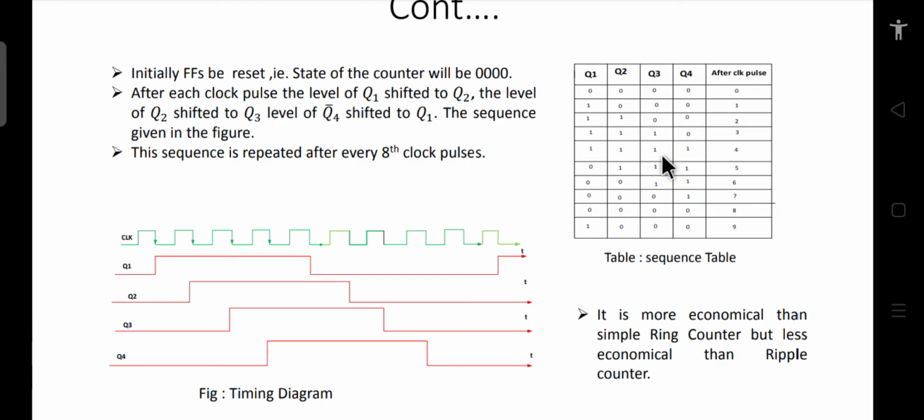Initially the flip-flops are reset, we always assume, and after the first clock pulse, as the feedback is coming not from Q1 but from Q1 bar of the last flip-flop, that is why it is able to count 2n states, because then it will become 00, rather than 1 appearing in between.